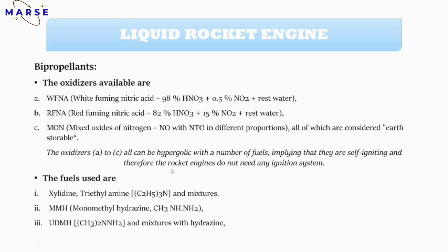So yes, hypergolic fuels and oxidizers imply that they are self-igniting. So that's why they are known as self-igniting propellants. And therefore the rocket engine does not need any ignition system. Understood? So that is the hypergolic one.